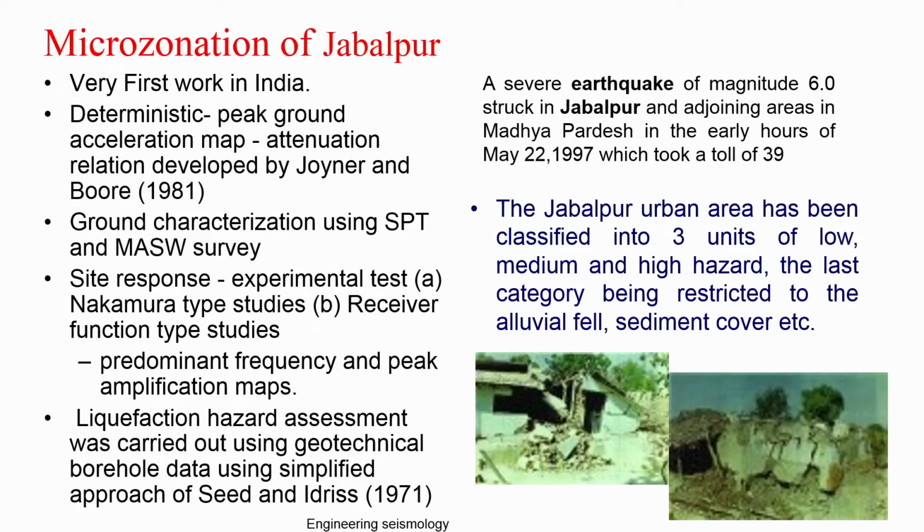They used SPT data and the MASW survey, and they also carried out site response studies by Nakamura type studies and receiver function, where they tried to estimate the predominant frequency, which we have discussed, and then the peak amplification map. Further, a liquefaction assessment was carried out using geotechnical boreholes with the simplified approach suggested by Seed and Idriss. So, even though we are not discussing liquefaction, site response and site characterization in detail, you should know that these are the work involved in the particular map. Okay, so they published a first level seismic microzonation map.